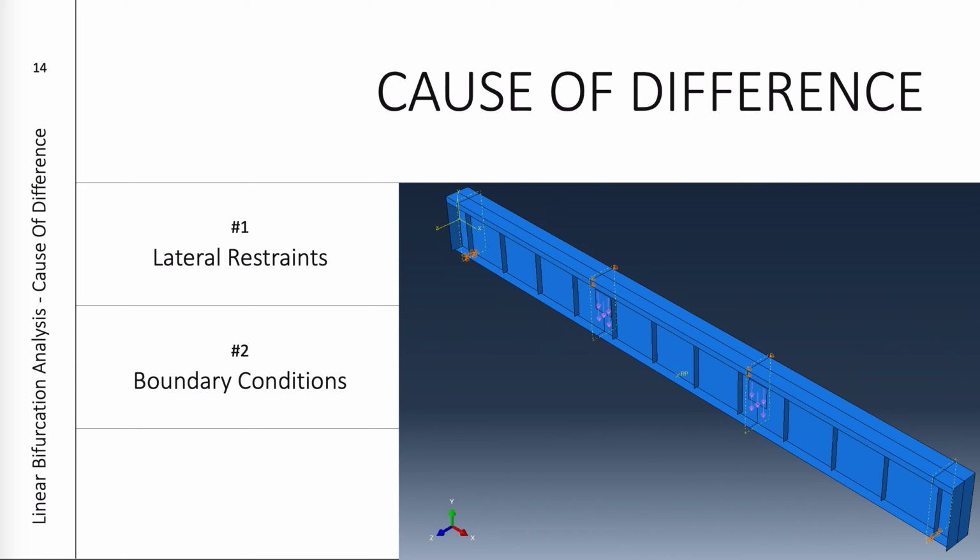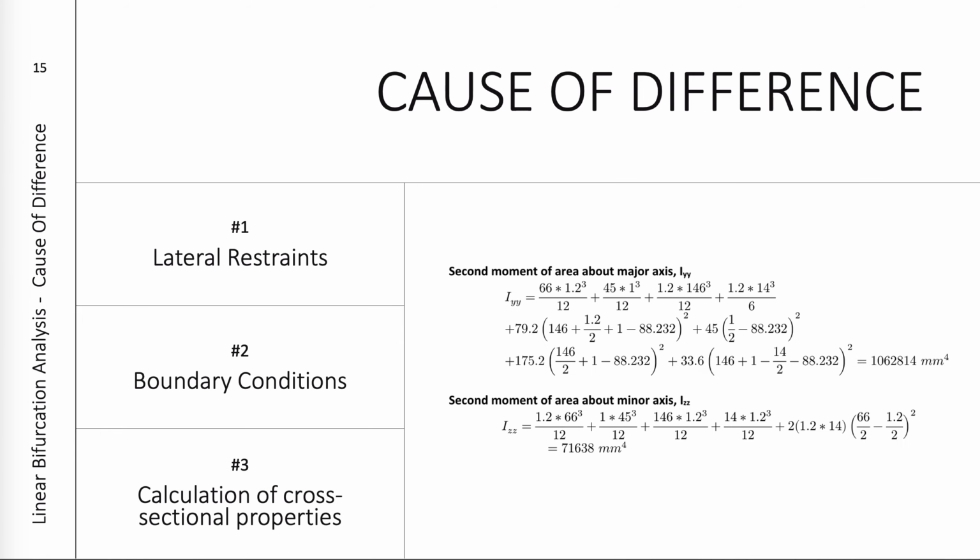This should be reconsidered such that one end is simply supported with fixed translation, while the other is free in rotation and translation. This results in a 52% utilization of LTB resistance.